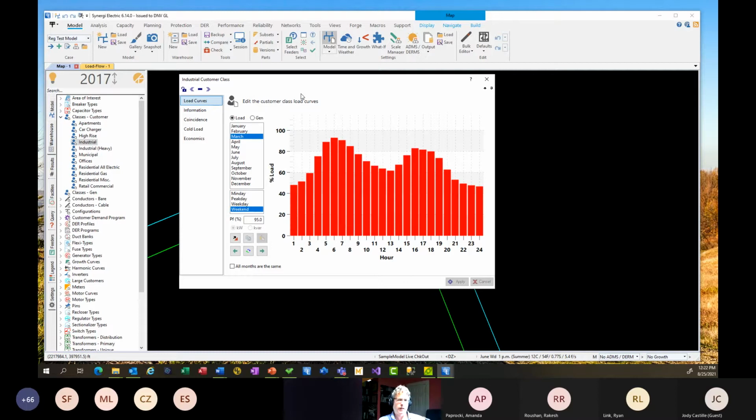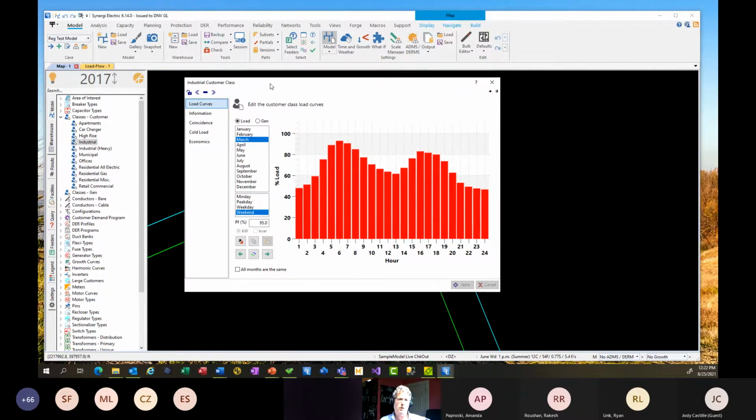You're going to need to do data processing and all sorts of statistical things to get load curves for different classes of customers. So maybe you have residential 1, 2, 3 curves, and maybe you've got different sorts of commercial rates or customer classes. You've got to get all these set up based on their recorded demand information, and then you have to get it assigned to the model.